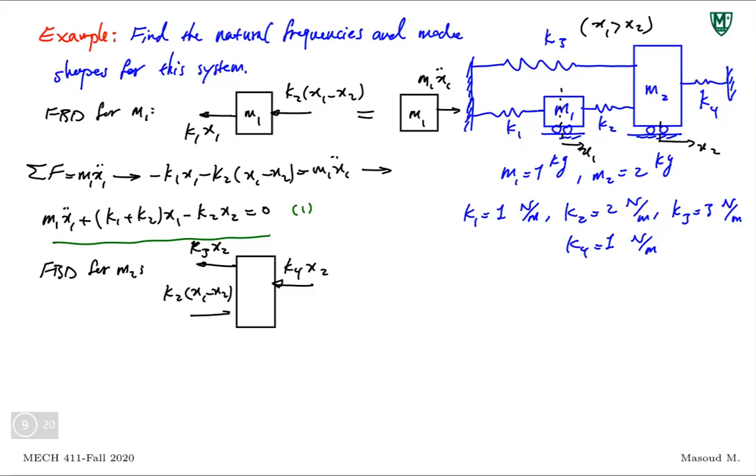All right? Newton's third law. Apply force to each other, one should be the opposite direction, the other one the same magnitude. If you don't want to do it, look at M2, M1. M1 is getting close to M2, so K2 is under compression, meaning that K2 is pushing M2 to the right. That's the direction. Magnitude, always keep it positive. Make an assumption X1 is greater than X2, so K2 is multiplied by X1 minus X2.